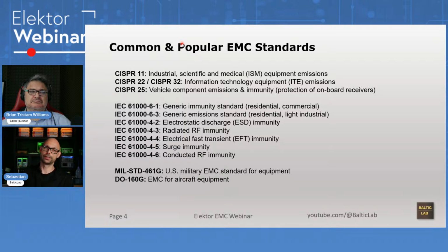What I, of course, left out in the intro are transient events like electrostatic discharge; surge would be a thing. Then in the automotive industry, you have things like load dump. This is where your battery contacts are loose and your alternator dumps all its energy into the electrical system. Reverse polarity. Everyone that's ever used a reverse polarity diode has done some sort of electromagnetic compatibility work. Then there are some very special ones at the bottom that I'm just mentioning because they appear in literature.